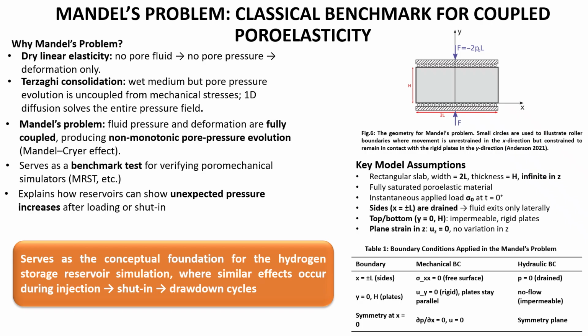When we change pore pressure during injection, we see the effective stresses go down, and also when we shut in, it creates some kind of pressure redistribution. Also, when we deplete or depressurize the reservoir, it induces non-uniform effective stress changes. So the Mandel solution would help us understand and interpret those results, which we would see.